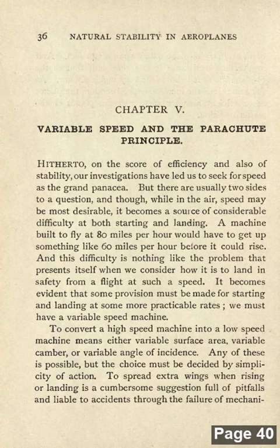A machine built to fly at 80 miles per hour would have to travel at something like 60 miles per hour before it could rise. And this difficulty is nothing like the problem that presents itself when we consider how it is to be stopped in safety from a flight at such a speed. It becomes evident that some provision must be made for starting and landing at some more practicable rates. We must have a variable speed machine.